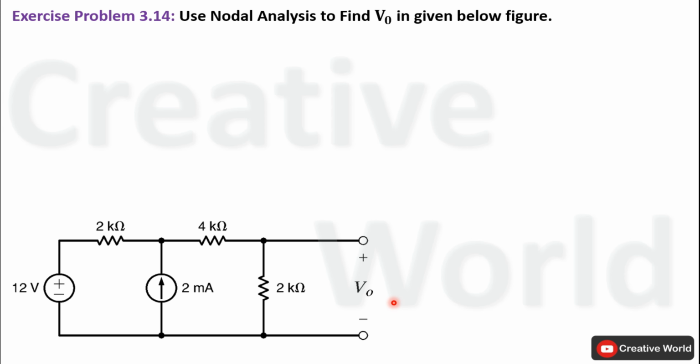We know that in order to apply nodal analysis on any network, we have to follow some steps. First step includes finding out the maximum number of node voltage equations that can be retrieved from that network. So using this equation, we can find out that figure. In this equation, n represents the number of nodes exist in the network. In this network there are 3 nodes, so 3 minus 1 will be equal to 2. So maximum 2 node voltage equations can be retrieved from this network.